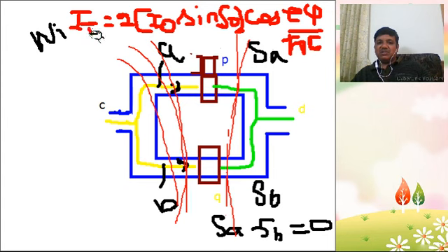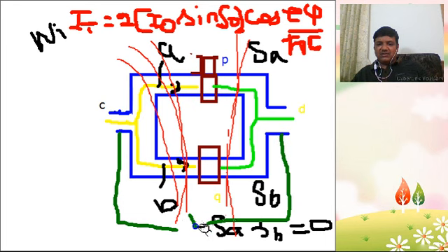So this is the expression for the tunneling current here, and we can see that by a small, feeble magnetic field, there will be a potential difference across the terminals C and D. So this is a magnetic field converted to a voltage, a flux to voltage converter. Very small voltage can be generated, and we can measure the magnetic field. So a feeble magnetic field can be measured.